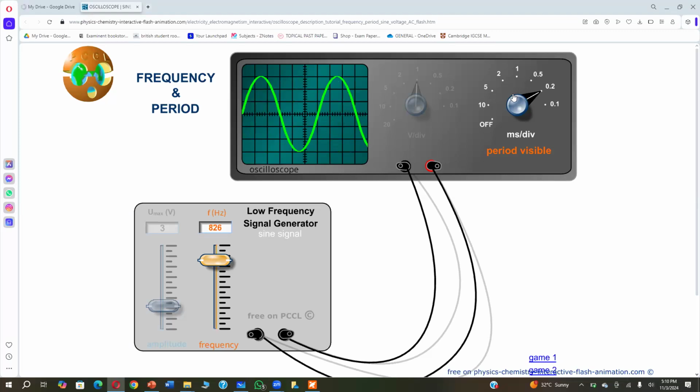When you take a graph paper from a graph book, you have to scale it. And this is what I'm doing. Now I decrease the scale further. Now it's too big, so now this looks better to me. I can go back. Now it is so shrunk that I can't see it. So this is called calibration. CRO needs to be calibrated just like a new graph paper has to be scaled 0, 1, 2, 3, etc. And then you can take readings.